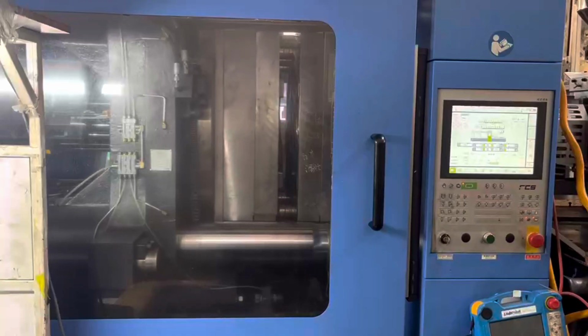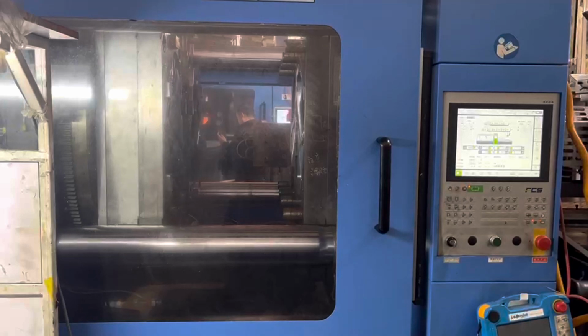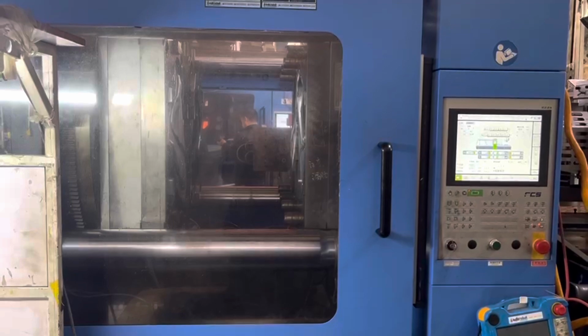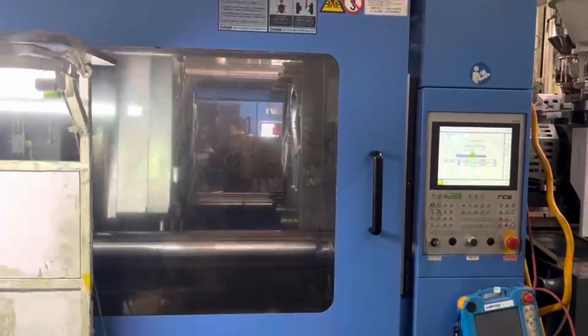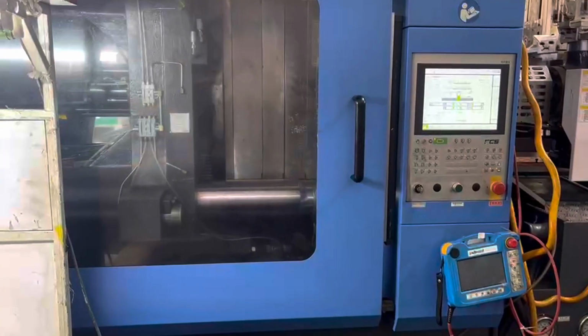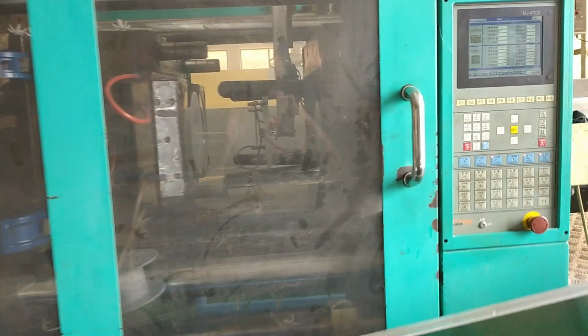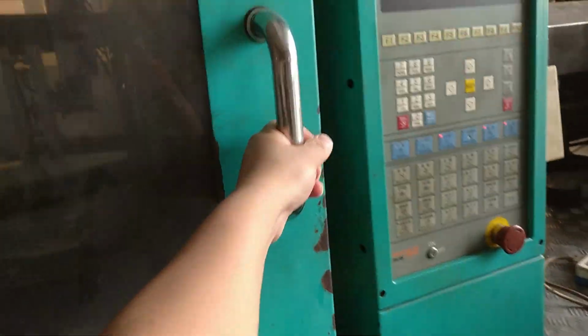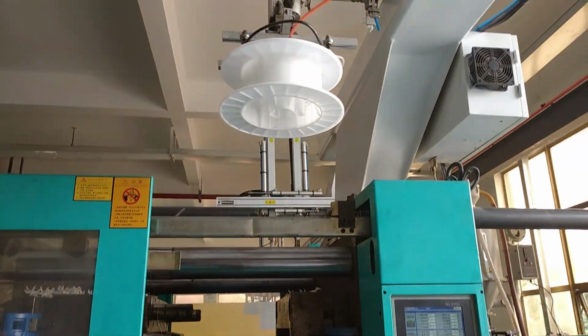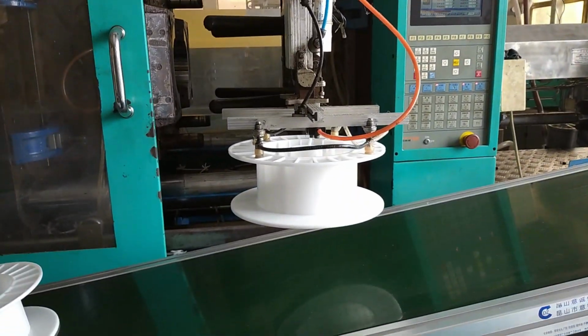The end of holding pressure is followed by cooling and curing, where the plastic product begins to cool and cure in the mold cavity. During the cooling process, the cooling system of the mold takes away the heat from the plastic, so that the temperature of the plastic product is gradually reduced until it reaches a temperature at which it can be demolded. Cooling time has a great impact on the quality and productivity of plastic products. If the cooling time is too short, the plastic products may be deformed. If the cooling time is too long, it will reduce productivity.